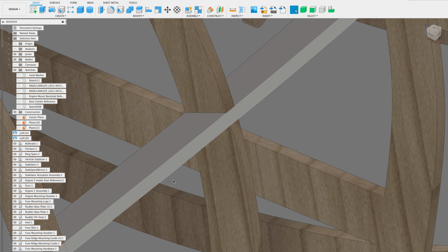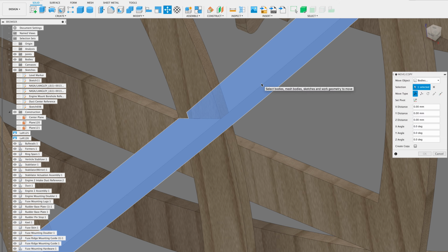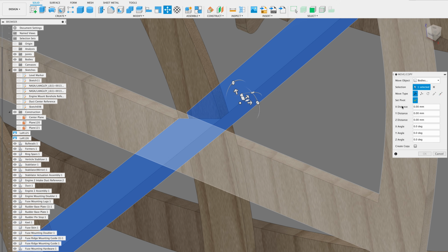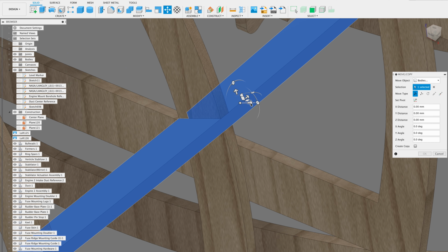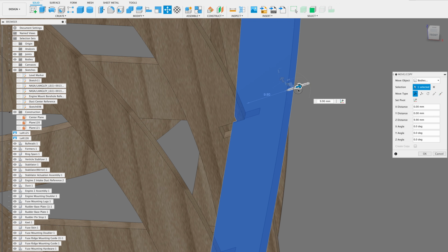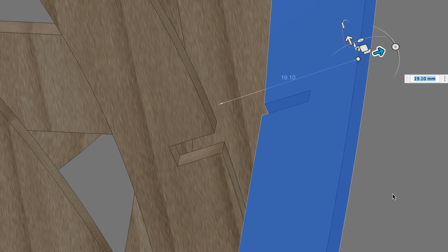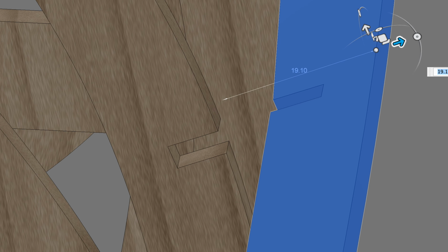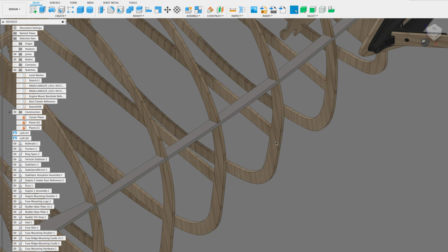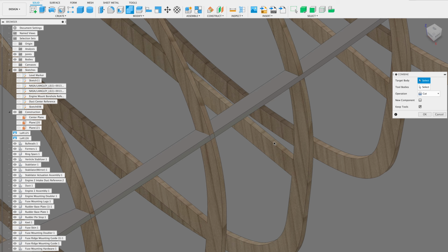And just to see how this actually works, I'm going to go ahead and select, press M for move, and I'm going to set my pivot point here so that we're moving in a direction that makes logical sense. And let's go ahead and pull this out of there. And now you can see we have got perfect fitting longeron to former. And cancel that. And all you have to do then is continue that process throughout the entire set.